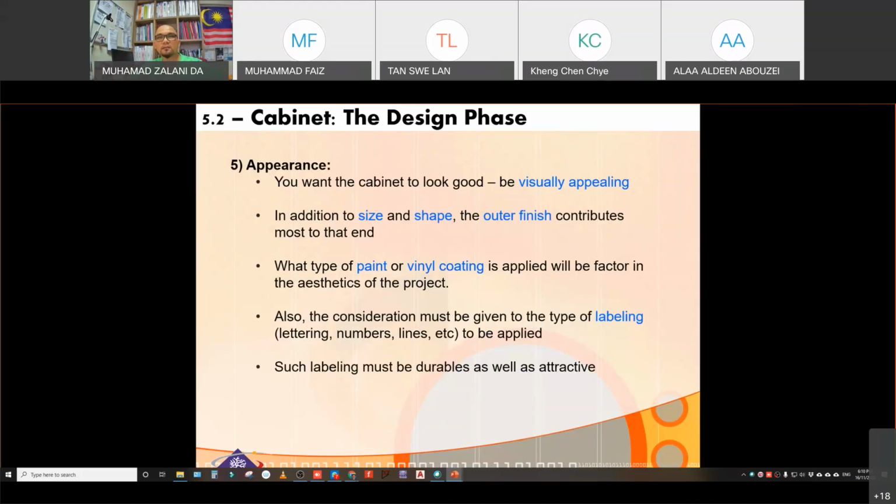When we are working on a big project, for example a project that has some wires, input and output, we have to make labels on that. The lines, for example the 5-volt level and the 12-volt level, are different. Grounding level, 5-volt level, 3-volt level, for example. So labeling is important when we do troubleshooting or repair of the machine, the prototype, the system. It should have some labeling.